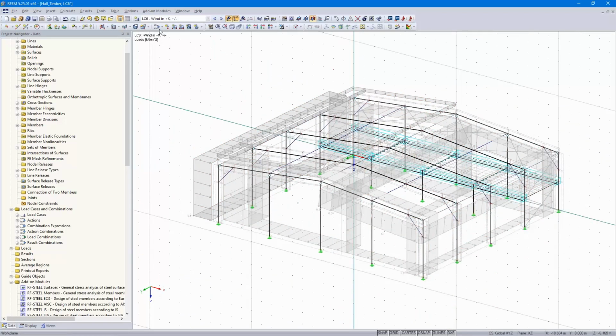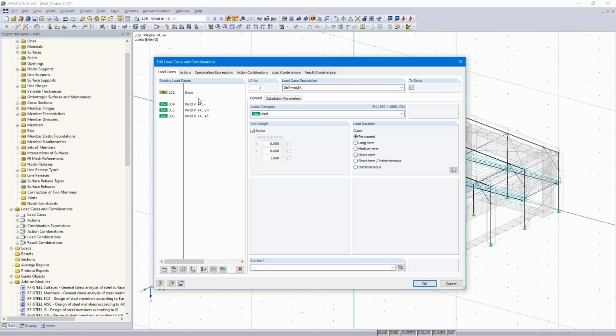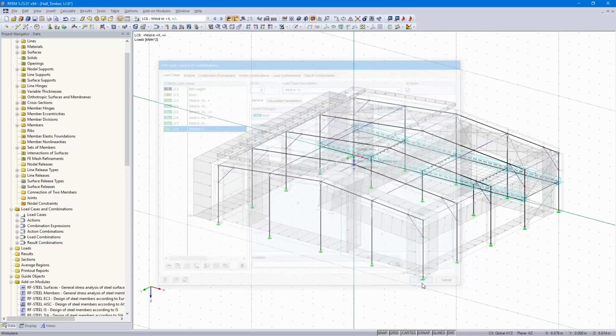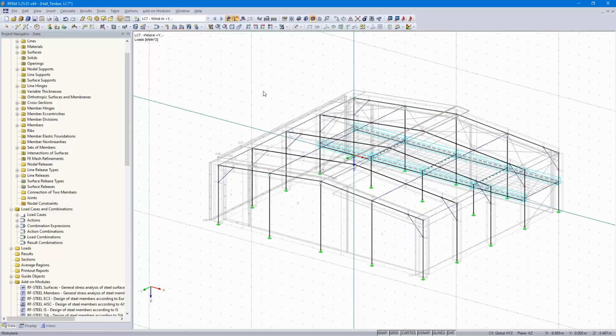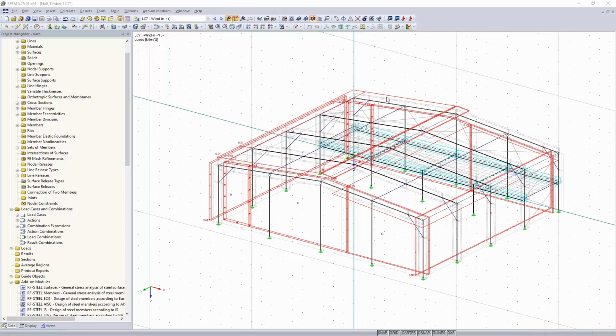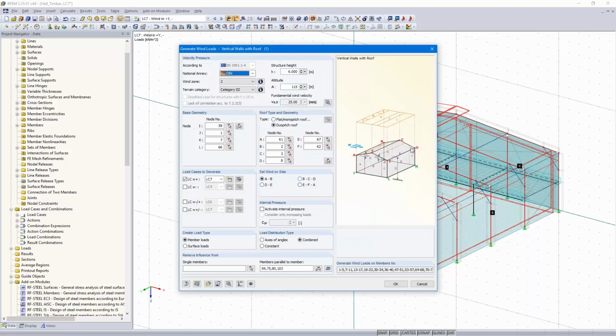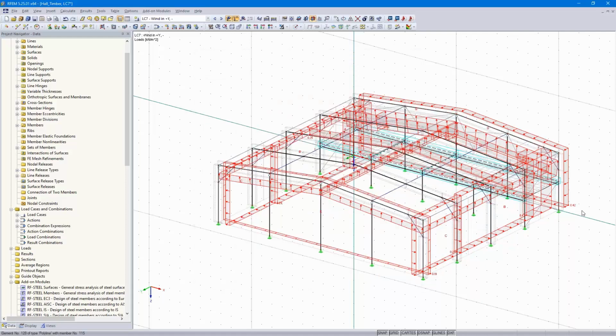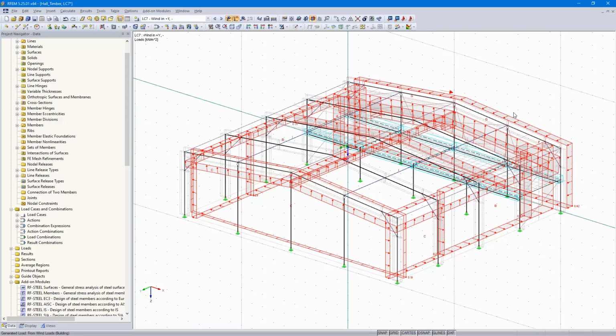Okay. So then we copy the wind load case number 3 one time, plus Y, and minus with suction, and I copy it again, minus Y and suction. Okay. And now I only need to change the parameters here by double click. I only need to change the direction from this side, B, C, D, and assign the load case number 7, suction, and I can press OK, and all loads have been changed from this side, plus Y direction.